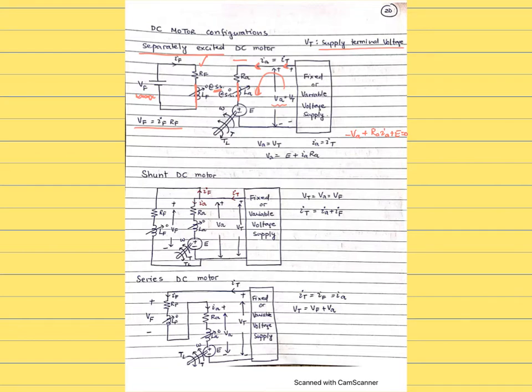and you remember in case of a motor, so this is the motor configuration, right? And in case of a motor, if you remember from the linear machine, let's say this was the conducting bar. So this was the load force. Sorry, my apologies, it was exactly opposite. Okay, let's do it like this. So there was the load force, and this was the direction it was going in. So that was the force produced by the magnetic field. So that's why you can see this is the load torque, and this is the developed torque. Okay, that's why they're drawn in opposite directions.